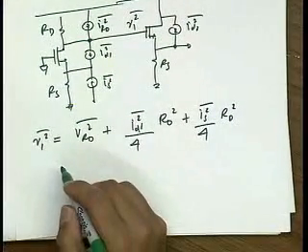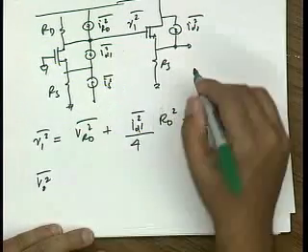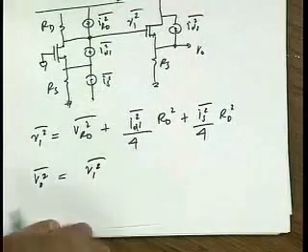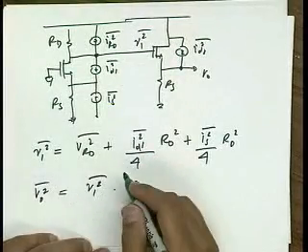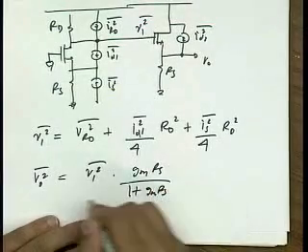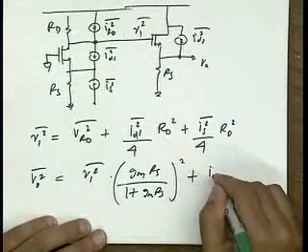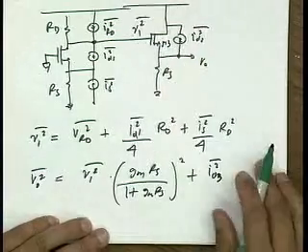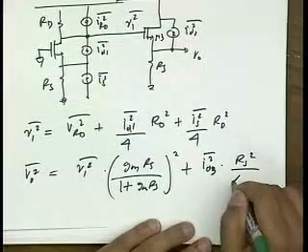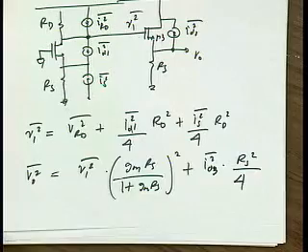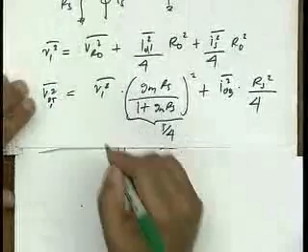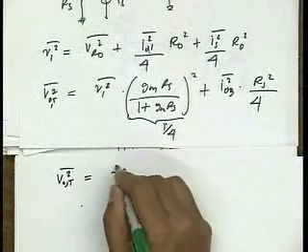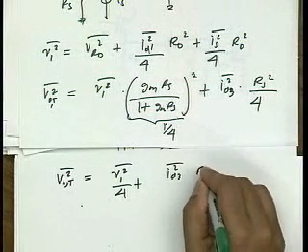Basically now I can say that the output noise, this is Vout, is V1 squared times the voltage gain of this stage, which is basically gmRS over (1 plus gmRS) squared, plus the noise of this device, M3, which we also figured out gets rejected by a factor of 4. Okay, so this is also a factor of 4, 1/4. So again, coming out here, this is the total output noise, is V1 squared over 4 plus I_drain3 squared RS squared over 4.